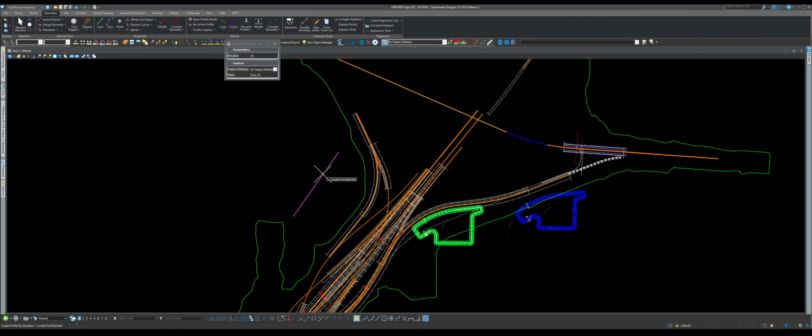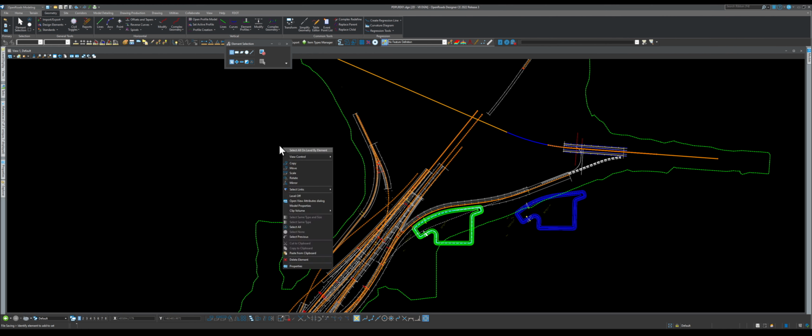And then locate the element itself. So what I'm telling it is basically give this line a constant elevation, a profile, basically. So make a 3D element. And by doing that, ta-da, it will automatically make the 3D view for us. See that? So that's one way, by the way. Most people think you need to have some type of terrain so you can activate the 3D. No, you can just draw a line, because the DGN for an ORD only needs some 3D elements to be initiated so you can go create the 3D model.